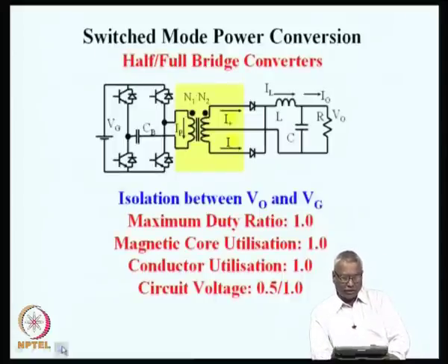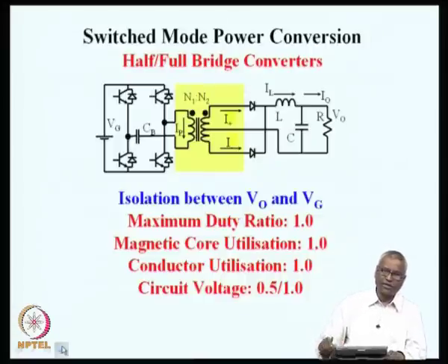Okay, now let us see again the bridge converters. At very high power levels, it is half or full bridge. At medium power levels, it could be single switch forward converter or the isolated flyback converter. At very low power levels, it could be isolated flyback converters or the lossy forward converter, because at low power, you do not care very much about the losses.